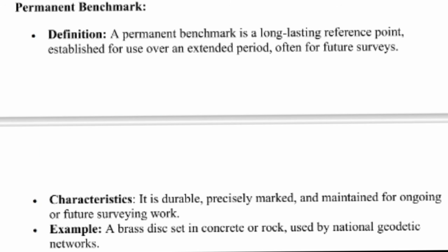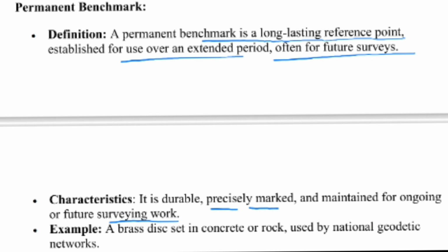Next will be a permanent benchmark. When you start the surveying, it is a long-lasting reference point. So if you want to establish it for the next day or for future surveys, you can use this permanent benchmark. That point should be marked precisely, and you can use this benchmark for ongoing future surveying.